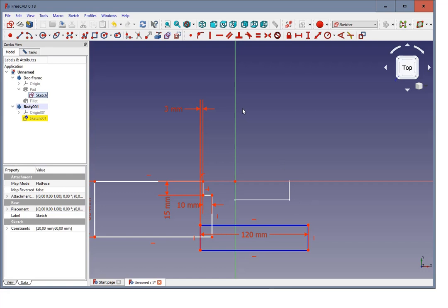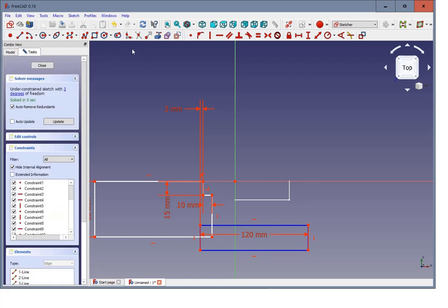And now we see that, and now we can create a reference, but we can't create a reference directly because we have this in a different body. So what can we do? Well, we can make a carbon copy out of this. So let's make a carbon copy and use the Control or STRG key while we're moving.